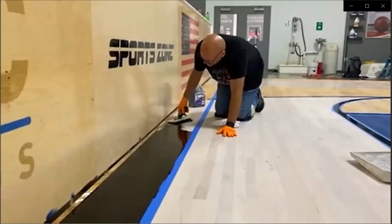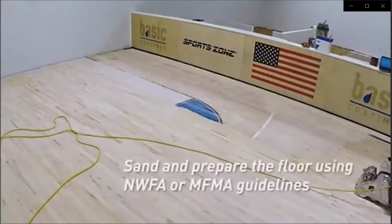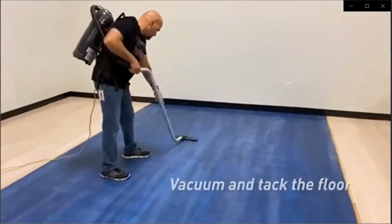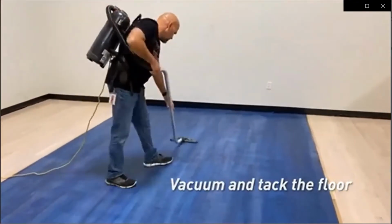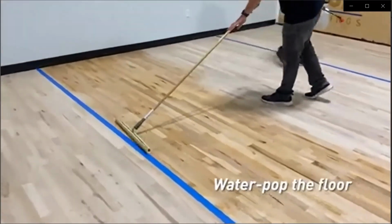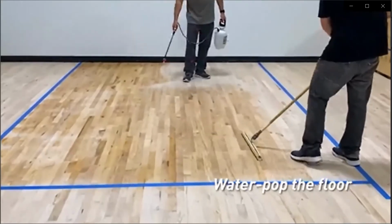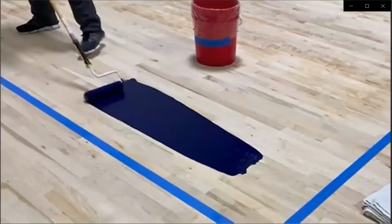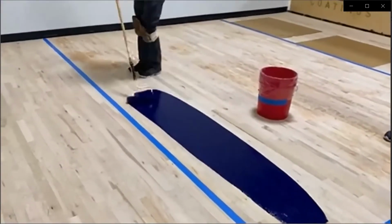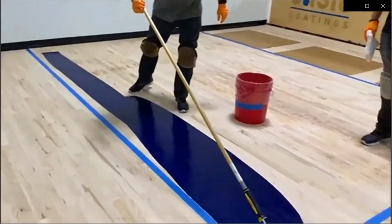When using HyperTone stains as a traditional wood flooring stain, prepare the floor using NWFA or MFMA guidelines. Vacuum and tack the floor to remove any dust or debris. As with most hardwood flooring stains, uniform water popping is recommended to open the grain and allow more consistent, deeper, and richer color penetration. Since this product is a unique water-based formula, there is no need to wait for the floor to dry completely before beginning application of stain, but do not apply to flooring that has standing water or puddles.